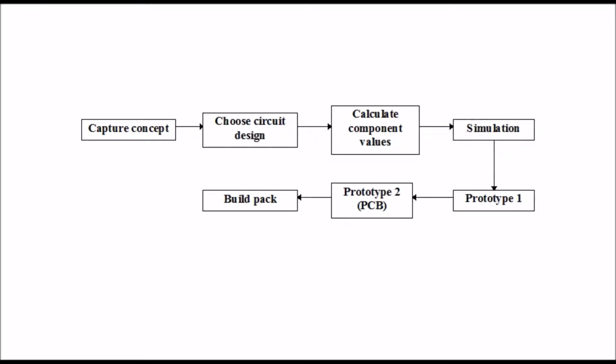When using simulators, bear in mind that you should use them to try out circuit blocks and not generally large systems. Putting in very large circuits tends to make simulators crash. So rather like prototyping circuits, keep it simple for testing. See the video on circuit modularity for more detail about this. And so without further ado, let's have a look at what's involved in simulating a circuit with a typical simulator.